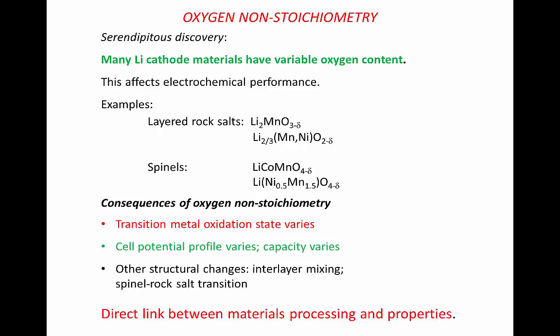And if the samples are cooled quickly, it turns out that they are quite different frequently from those which are cooled slowly, because at high temperatures the materials are oxygen deficient, and if they are cooled slowly they have time to reabsorb oxygen, but if they're quenched instead then they remain as being oxygen deficient.